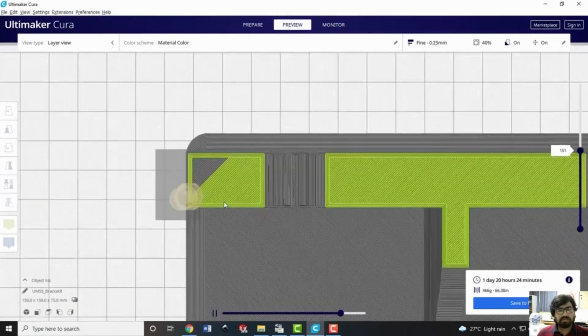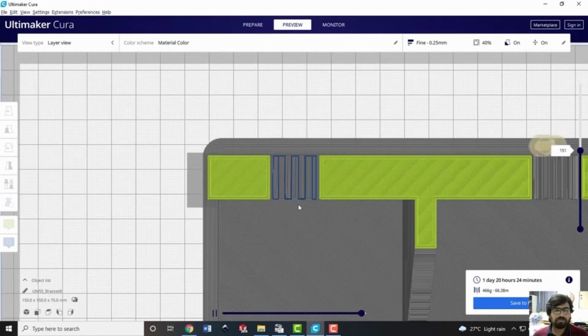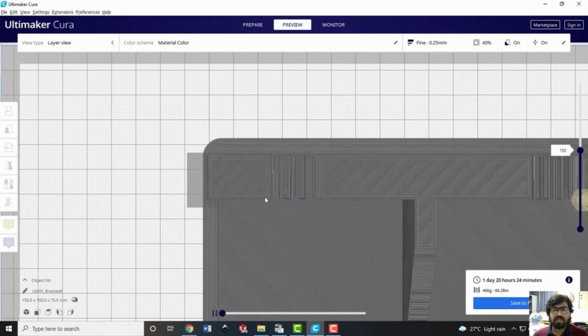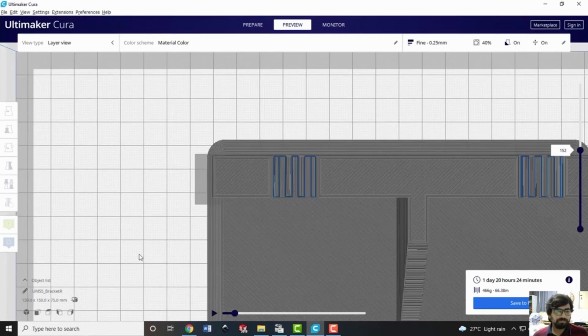Then after that we know that this nozzle is going back to this prime tower, and here it will deposit some material from the extruder 2, because now it is going to deposit the support material. And now you see that, and it can be noticed that in this case right now the deposited material is not having the same area filling density as it was corresponding to this main material deposition. This is because I have already explained. Anyway, I am going to remove this support later on. So it is good to deposit this material always with the less infill density so that we can easily break it later on.